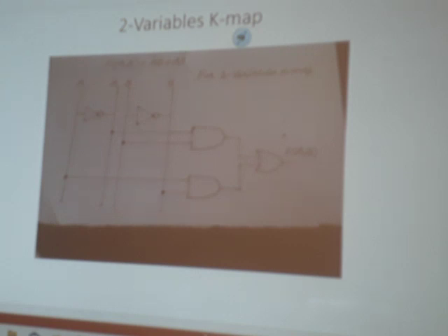So again we will have an ANDed term. These two outputs of the AND gates are connected with the inputs of an OR gate, so the OR gate will give us the same function, the addition of the two terms at the output.